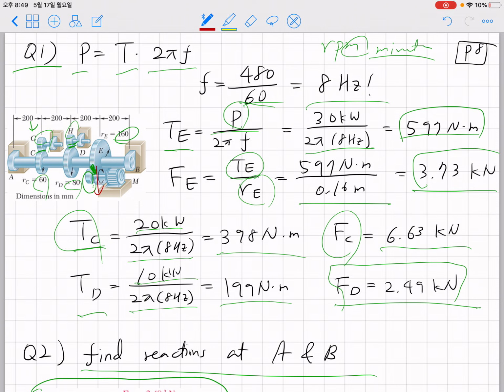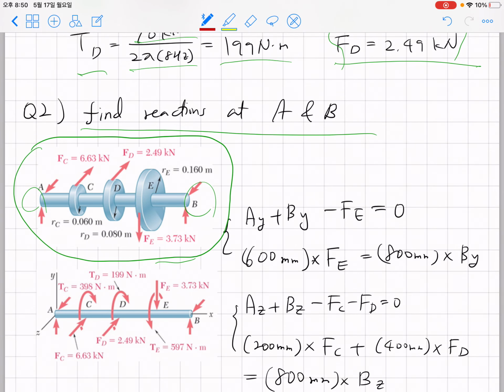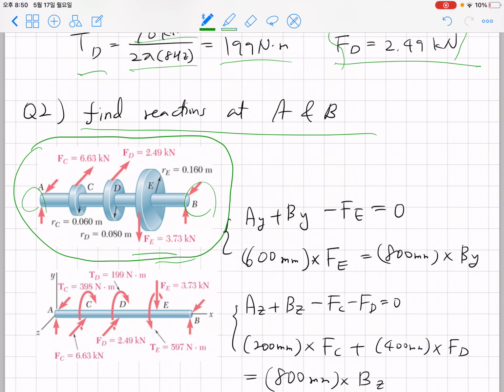As a reaction, because this gear wants to rotate here, but due to the resistance here and there there is no acceleration, you can expect that the forces at point C and point D will be in the opposite direction to the rotation direction. So this is how we draw the free body diagram: one vertical downward and two horizontal, going deep into the surface you are looking at.